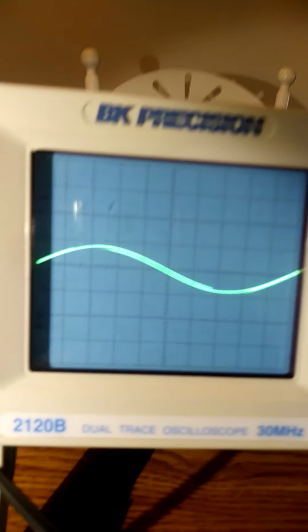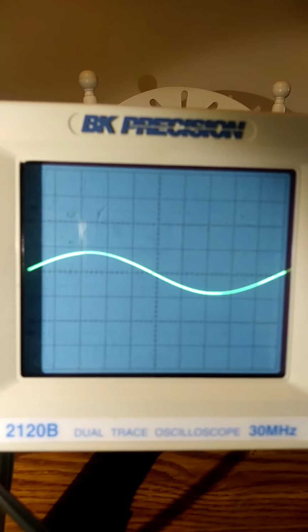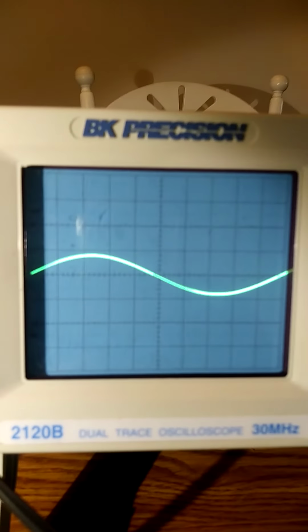We're going to set the volts per division to 5. Okay. So now I have changed this knob to read 5 volts per division, and you can see that the waveform has changed. So now you're going to draw this waveform on the next block on your data sheet.